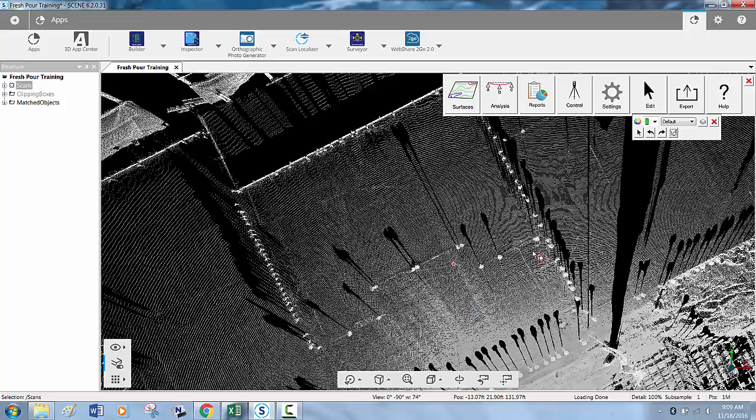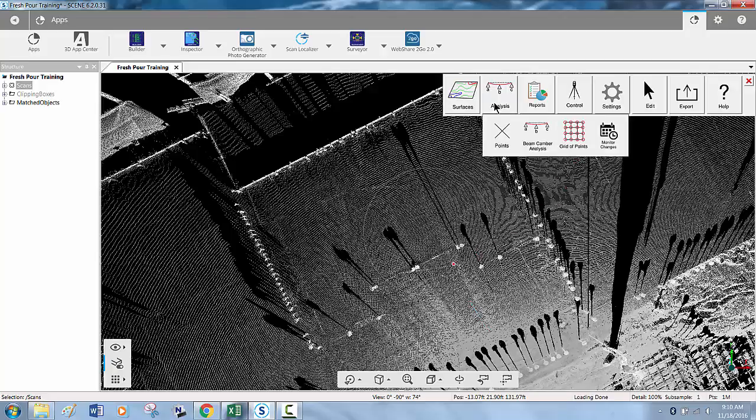So we've scanned in the future, we've registered this to the project coordinate system, and I've settled it by that little trick there. I've made it drop 1 foot lower than the grid of points that I had created a moment ago, and this is to simulate the settling that can happen over time. But now we've got an old CSV file and a new point cloud. We want to run an analysis to monitor the changes.